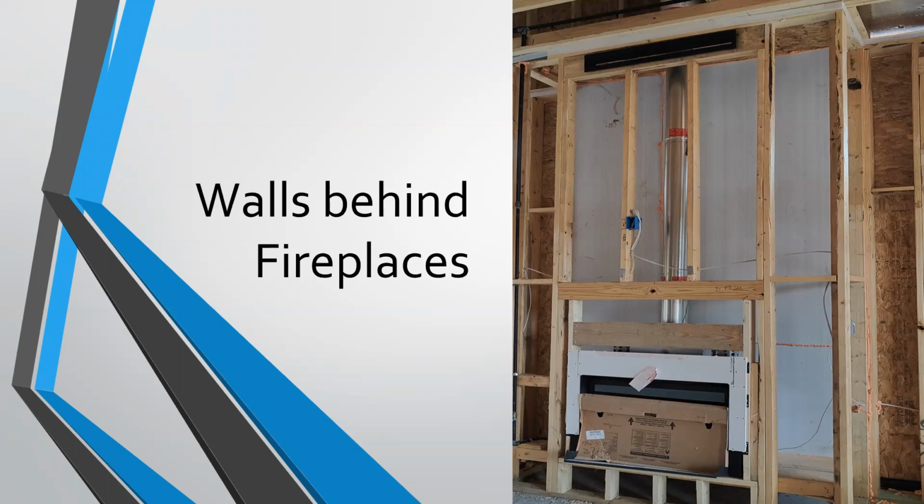If you leave it open to interpretation, now everything about this matters, and you have to decide where your starting and stopping point is to align the thermal envelope with the rest of the house. This is the right way to do it. Back to that scenario of thinking of it as a square box, and now you built a fireplace in front of it. You still need an air barrier inside of the insulation on that back wall. So this is the correct way of showing how it should be done.